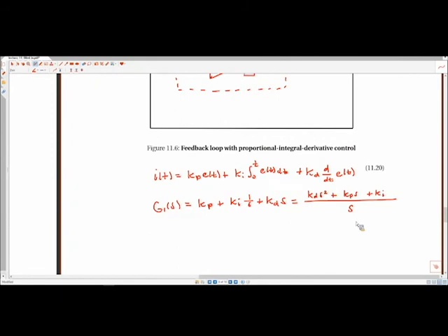Yes. So I worked very little with PID. I worked on hydraulic systems. As a general rule of thumb, a high proportional term, medium integral term, and a pretty low derivative term, would that be the same for these scenarios? Yeah. So usually you have a proportional term, then an integral term which is somewhere between 50% and 100% of the proportional term, and then the derivative term is usually about 10% of the proportional term. Yeah, that's a general rule. That doesn't hold, obviously, on every system. Some systems have a lot of damping in them, and some have very little damping naturally. So that adjusts the derivative term. But yeah, that's a really good starting point.